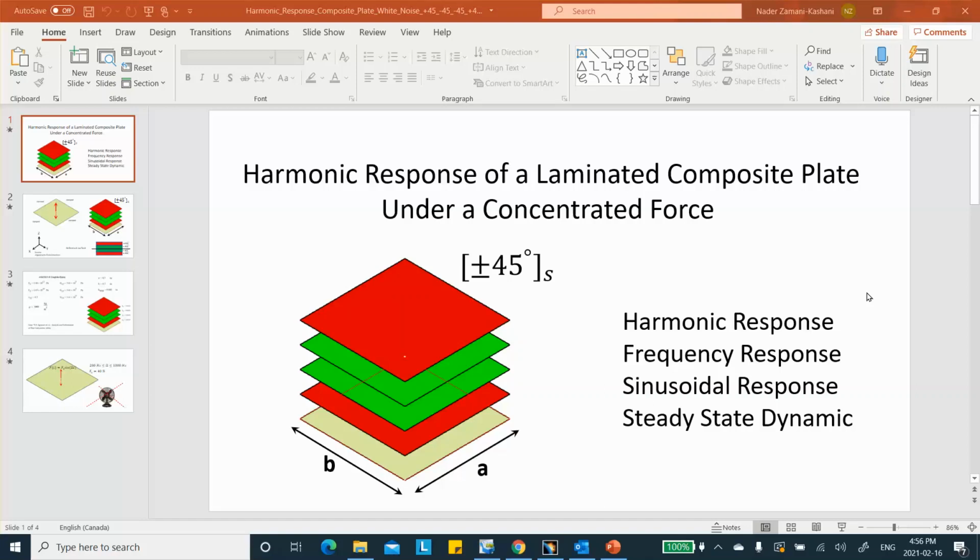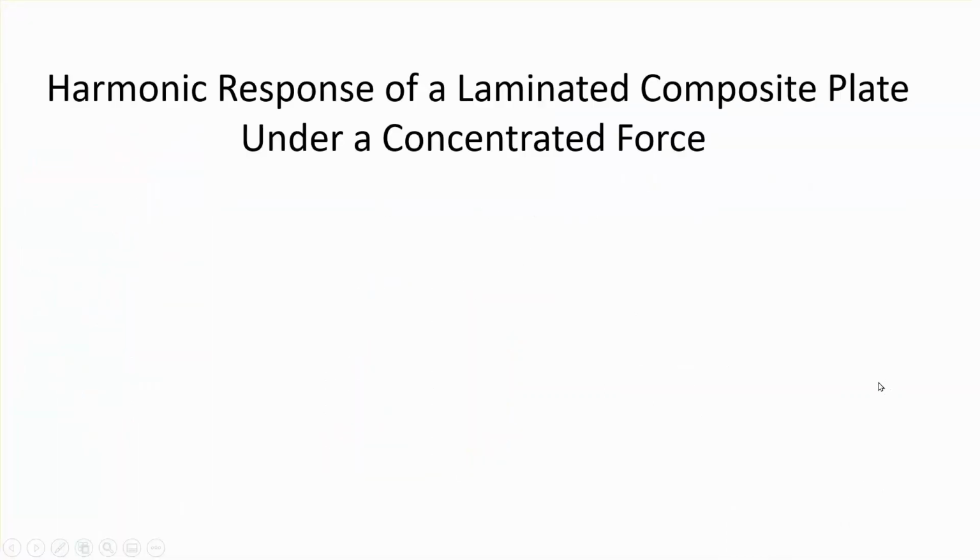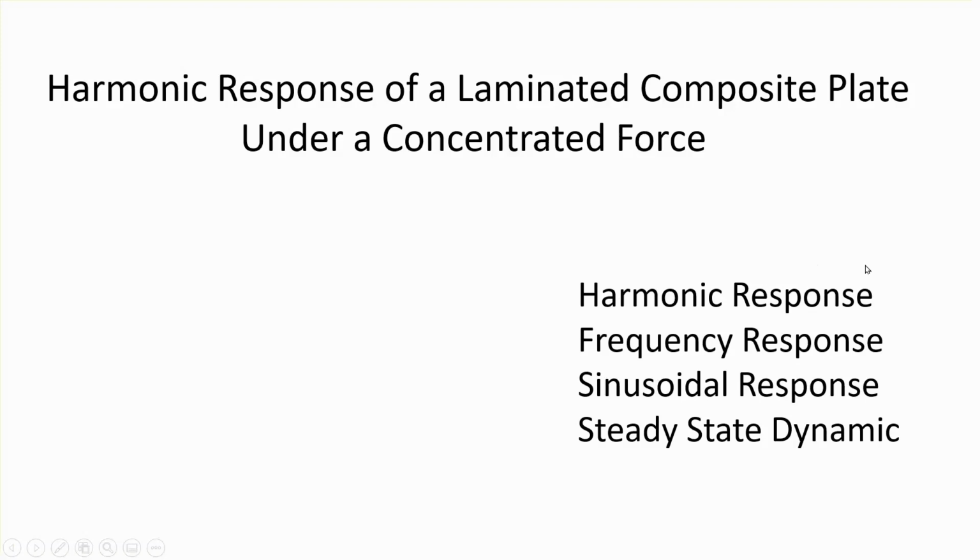Okay. Now, let me go ahead and get this into the slide mode so that we can discuss it better. A situation like that, where the force or the excitation is not inputted as a function of time, but instead as a function of RPM, or let's be more accurate, as a function of frequency, is called a harmonic response of a composite. Now, this also comes under other names, for example, frequency response, sinusoidal response, steady state dynamics, etc.